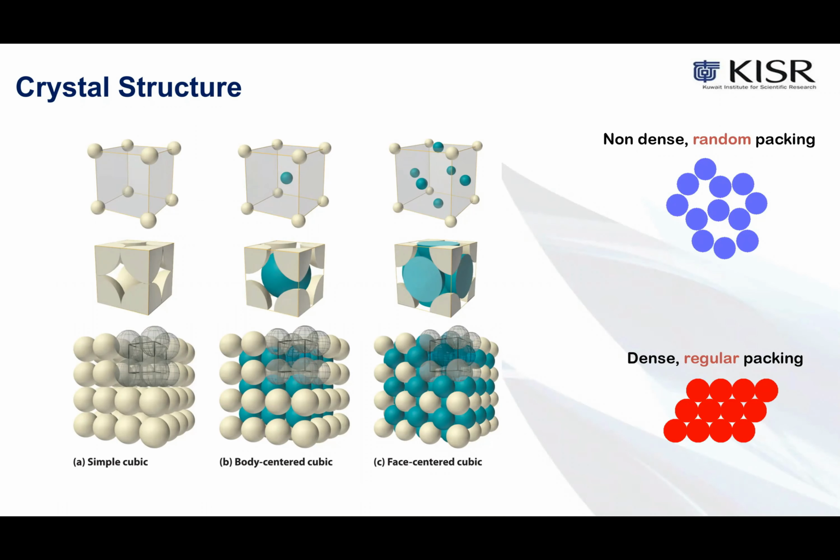It can be either a face-centered or body-centered cubic cell. Deviation from these structures is seen when particles have a reasonably high percentage of their atoms at the surface, and the variation in the surface energy starts to disturb the forces between the atoms, giving the normal equilibrium packing.